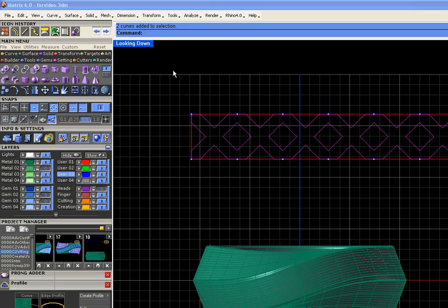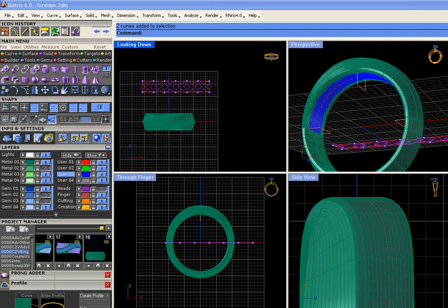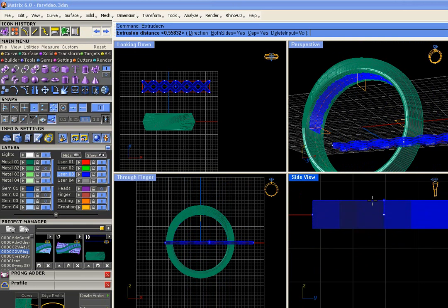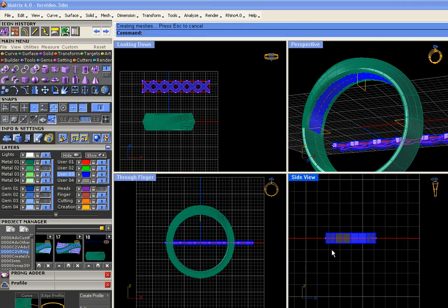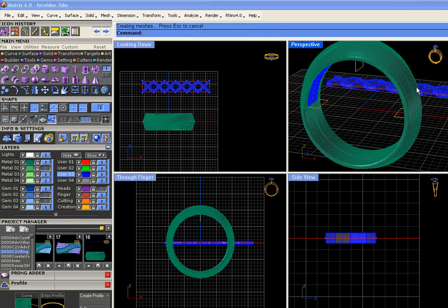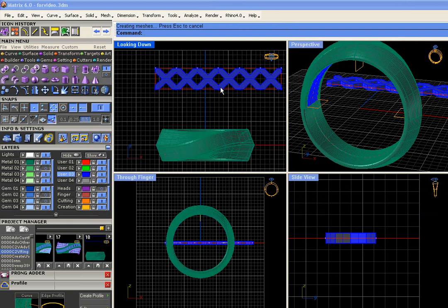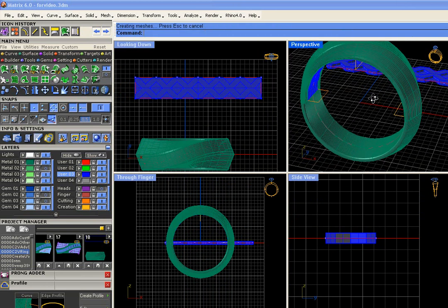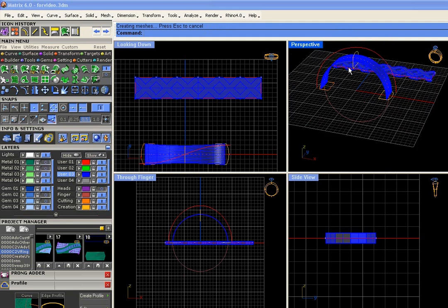And in the solid menu, we're going to go ahead and extrude this. The extrude command, straight option, and just give it a little thickness, enough to be created here. Okay. We now need to sweep the surface that it's on with a sweep 2 between the 2 rails and the 2 profiles. Okay, that corresponds with our surface up here.